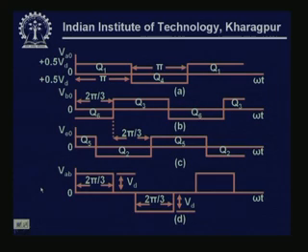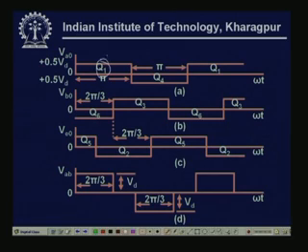Now consider any one phase, say VA. If we switch on the corresponding switch, VA can be made to vary. So Q1, Q4 we are switching. Q1 is A plus, this is A minus, and so on. So by switching A plus and A minus we can make it vary. Now if we keep varying the B phase, which is Q3, this is B plus and this is B minus, and we switch them in a similar fashion, but now it is phase shifted by 2 pi by 3.